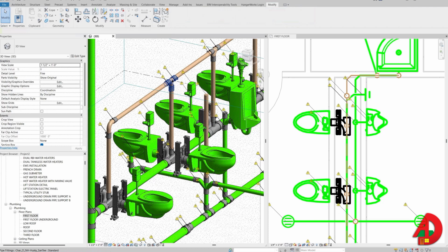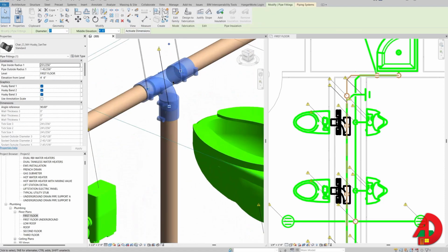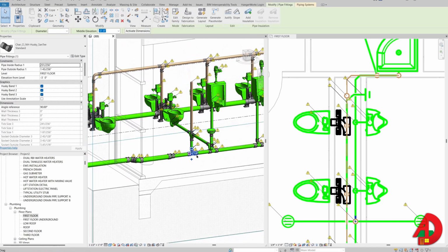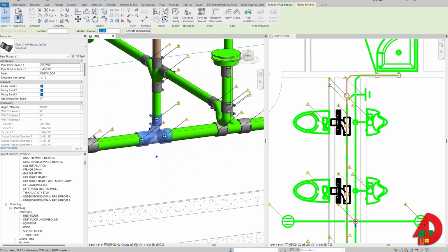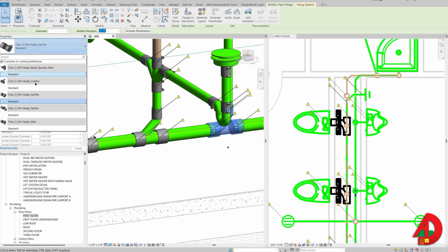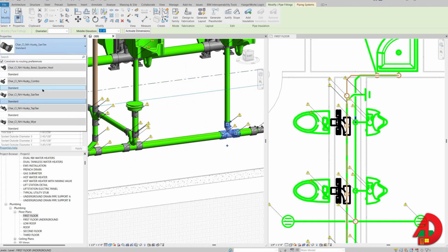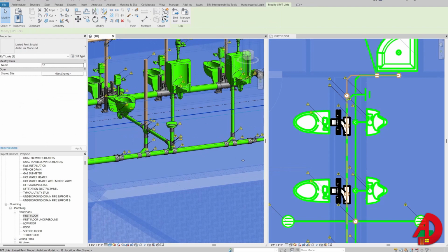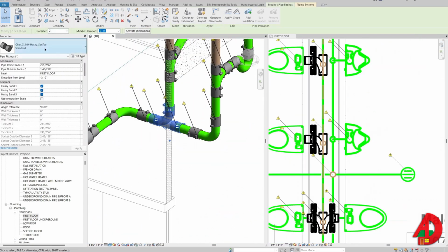And I want to flip this again. It might be hard to see these tiny flip arrows. It always helps if I zoom in a little bit, and since I did that for the vent, I will do the same for sanitary system and turn these fittings into combos. And the only reason these cast iron fittings are interchangeable is because I created my own, and I have a video about how I did that. I just need to keep in mind that for all this to work I need to have enough space.